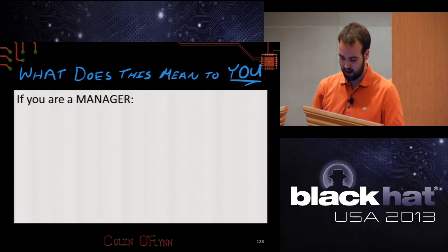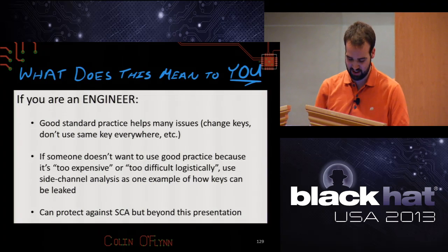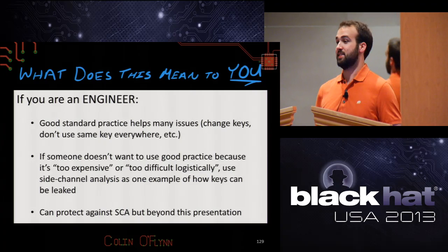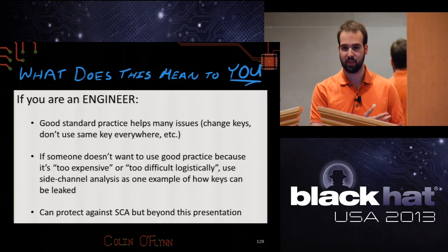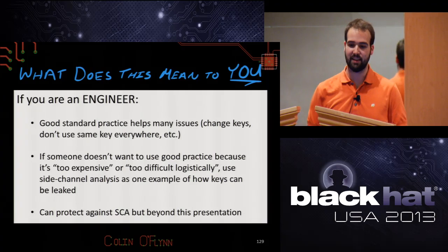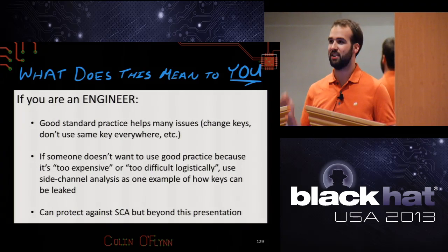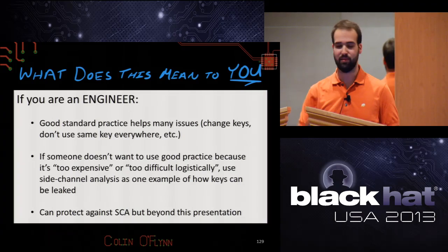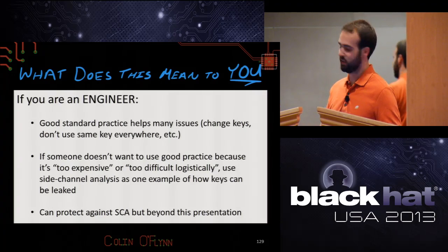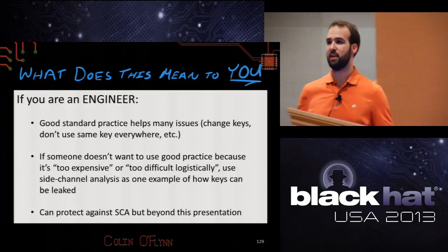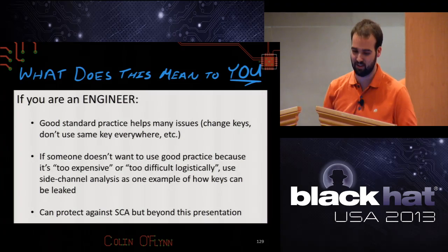So for the high level, if you're a manager, I don't really know because it's all technical to me. If you're an engineer, good standard practice does help this issue already. So if you use the same key in all your devices for the bootloader, you probably know that's bad. The problem is that a lot of people don't want to use good practice because they say, well, that's a hassle. I'm not going to have different devices with different keys in their bootloader and then different firmware files. So maybe this is a good way to point to say, well, here's a reason we should do it, because here's an easy way people could be breaking our systems. And so you can use this to point out why we should use good standard practice.